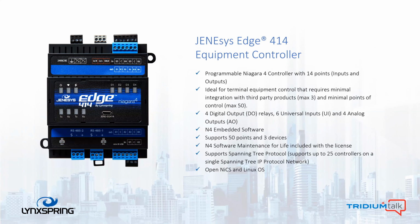Okay, starting to look similar, but the 414 varies differently from a 514 and especially from a 534. Same way as a 514, it has 14 points of I/O. However, it has the same communication capabilities, but it does represent itself with different Niagara licensing. It's the same Niagara, but we limit it to 3 devices, 50 points.